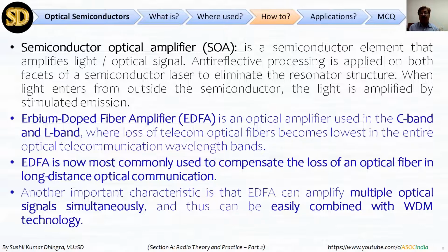Don't forget, nowadays internet is also coming from optical fiber, and these optical fibers are using EDFA amplifiers. This EDFA amplifier has another important characteristic: it can amplify multiple optical signals simultaneously. So many signals are coming and all are being amplified. A single-channel amplifier handles one signal, but this one is multiple, combined. It can combine them with wavelength division multiplexing technology.